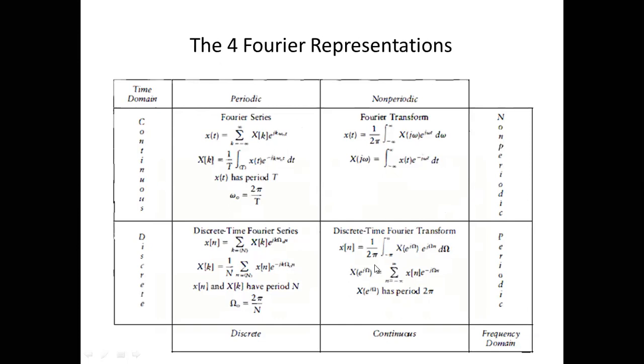So what is there in Fourier, by the way? Fourier is all about converting data from time domain to frequency domain. You have had the Laplace transform, which converts from time domain to S domain, and you might have studied the Z transform also, which converts from time domain to the Z domain. This is a specific extension of your Laplace: you replace S by j omega.